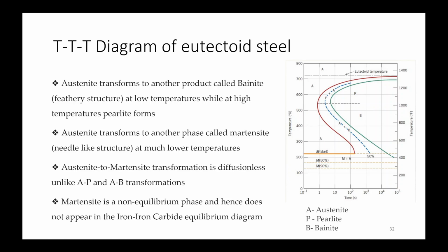You will be getting different temperatures, like alpha is forming in a particular temperature range. So if you are in the hypoeutectic region, then alpha is forming, then the eutectic mixture is forming at a single temperature. So that's what will be happening. The mixture has a single melting point, like pure elements. That's what it corresponds to.